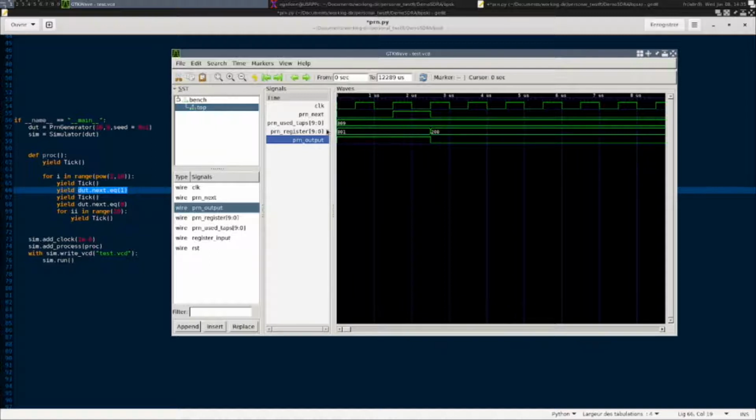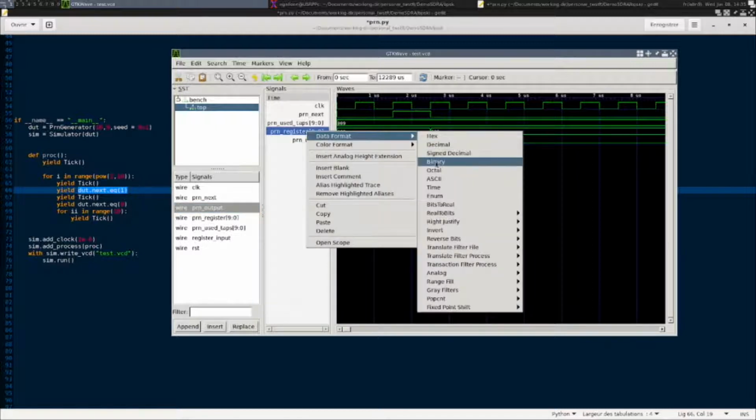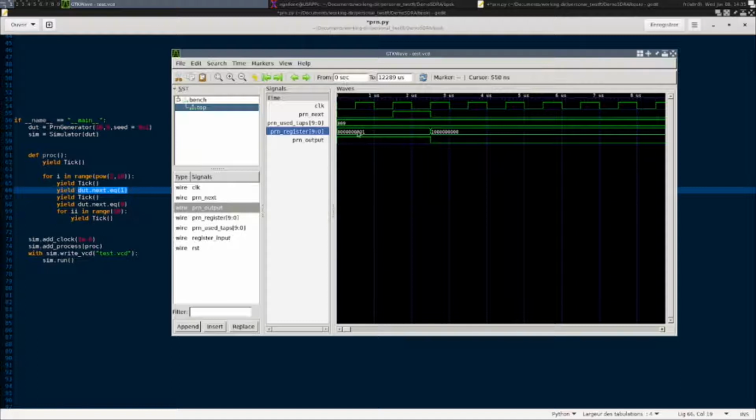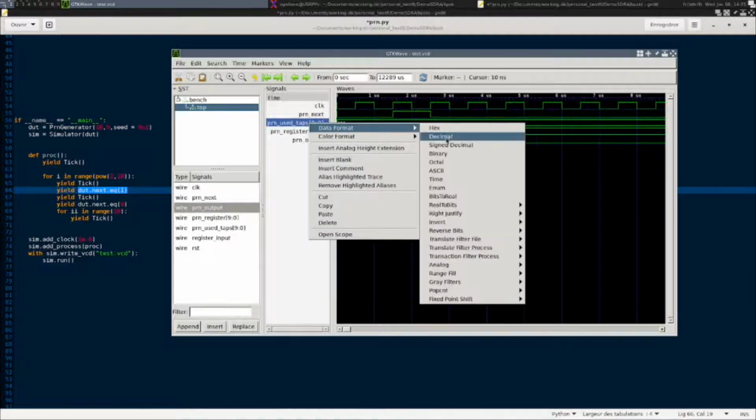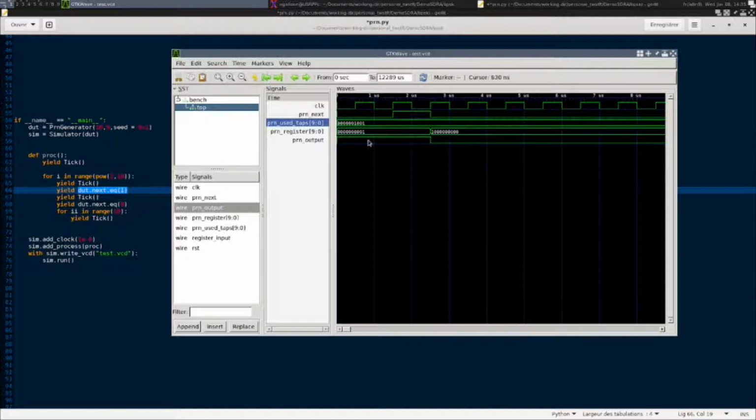So if you want to see in a clearer way the shift of the register, maybe it's interesting to see what the values are in binary. So here you see that the taps we use are the bits in the first and fourth position. We make every time an XOR operation between all the bits of positions 1 and 4. Here we have 1 XOR 0, which equals 1, and that's why the value inserted here is 1.